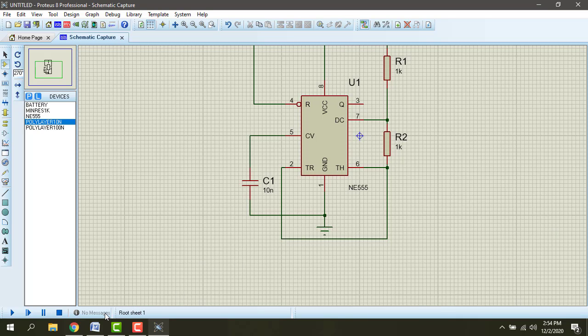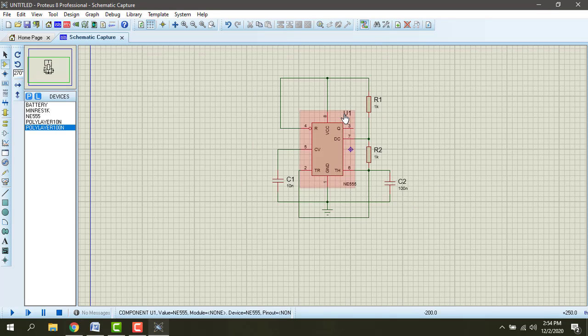And from that we have one capacitor C, 0.1 microfarad, with design value 100 nanofarad. It's going to be connected to the ground. Okay, I think connection is over. I'm going to connect a battery, supply voltage. Plus is connected to positive, minus is connected to ground.